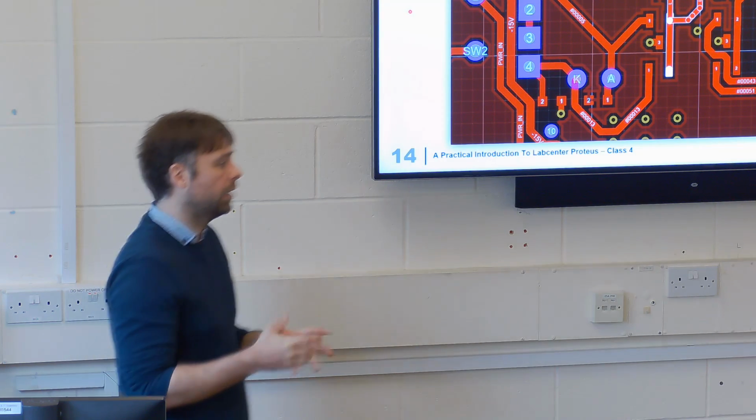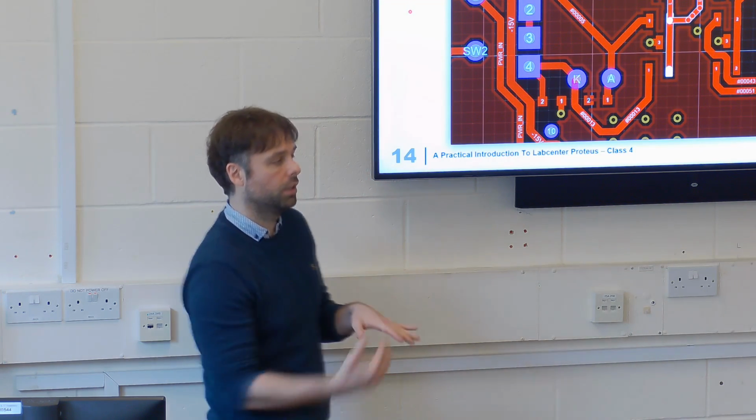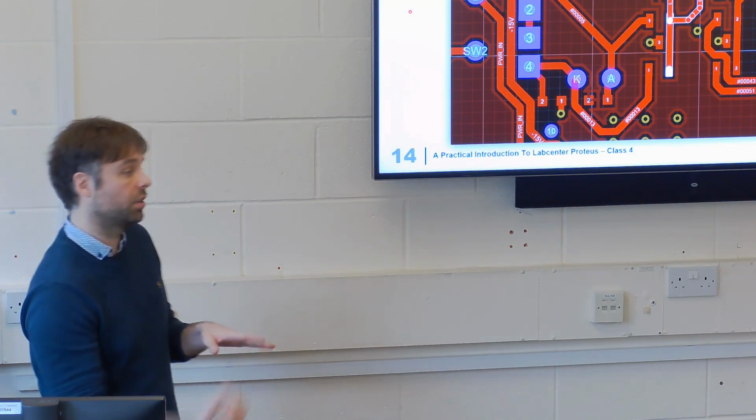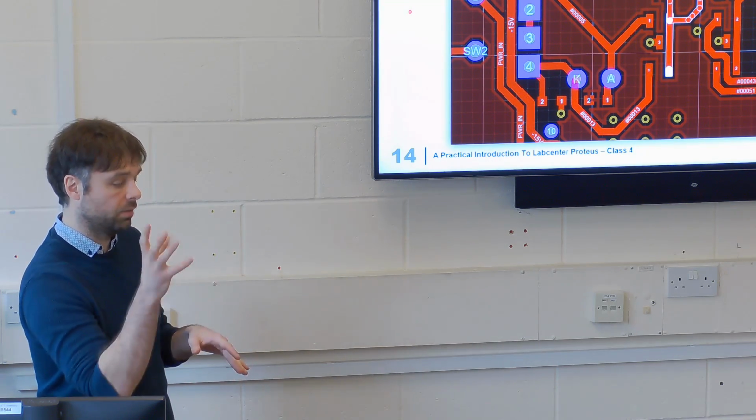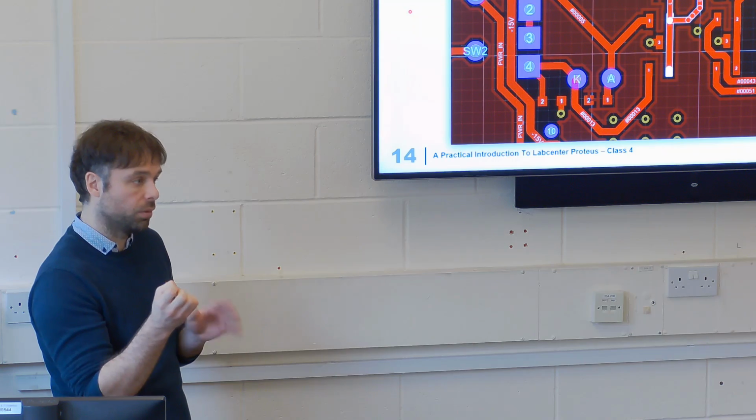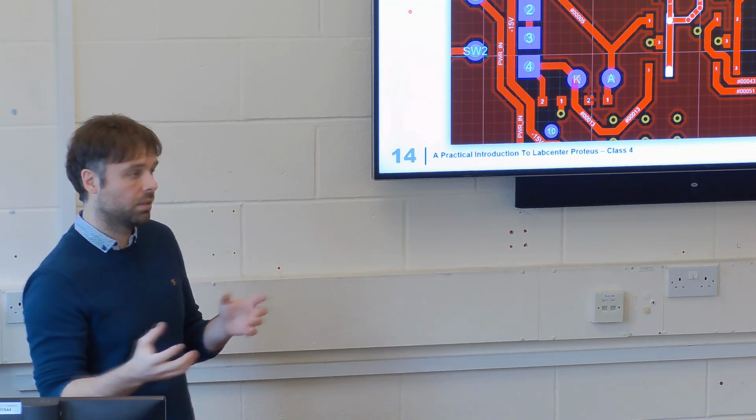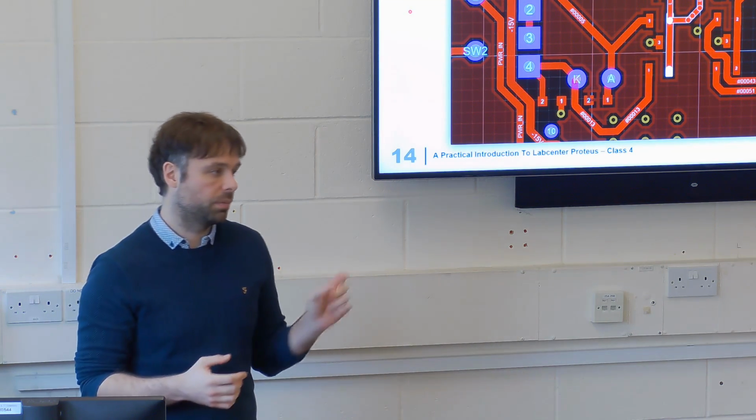Increased inductance is bad, because that's the thing that will restrict current flow when an IC, for example, switches from a 0 to a 1, and you've got that digital level shift. It requires current to do that, and especially the quicker it is, the more current it needs. That's why you want thicker traces.